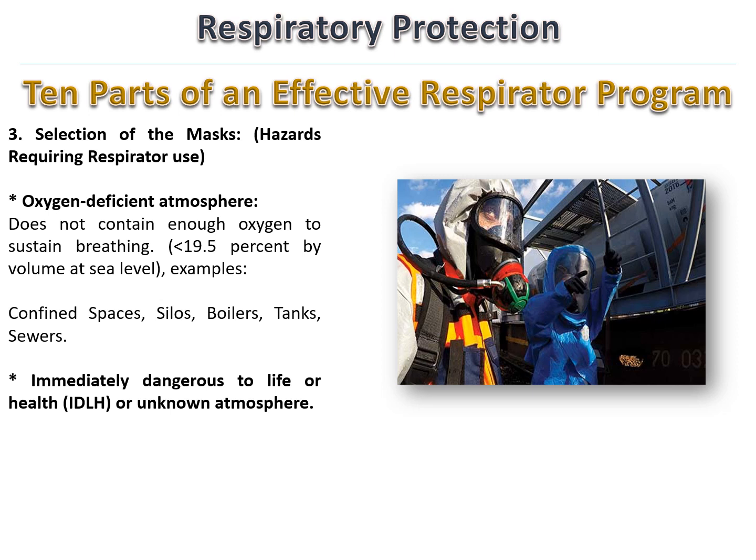Three. Selection of the masks, hazards requiring respirator use. Oxygen-deficient atmosphere does not contain enough oxygen to sustain breathing. Less than 19.5% by volume at sea level. Examples: confined spaces, silos, boilers, tanks, sewers. Immediately dangerous to life or health, IDLH, or unknown atmosphere.